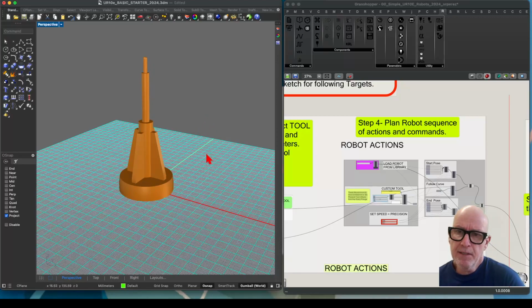The important thing here is that we have exported that geometry and saved it on your hard drive as a mesh, and then we import it back in to use with our robot. The other important thing is that it's pointing up at 0, 0 when you import it. So we'll go over this together, but this is basically what you should see when your robot simulator is turned off and you're not previewing the robot arm.